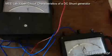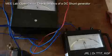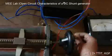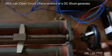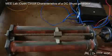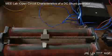Once you're done with the increasing voltage, you need to take down the readings for the decreasing voltage. For that, you just have to go in the reverse direction, little by little, gradually cutting in the rheostat, and note down the current as well as the voltage across the generator. You can take down one reading here. At regular intervals, you can take down the readings.